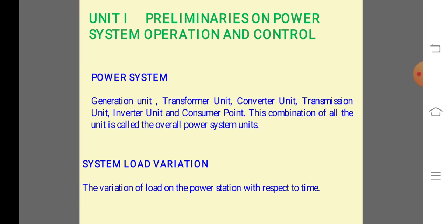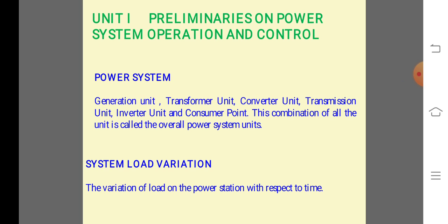The governor senses the speed and gives a command signal. Governor control is used to control the speed of a prime mover. A governor protects the prime mover from overspeed and keeps the prime mover speed at or near the desired revolutions per minute when a prime mover drives an alternator supplying electrical power at a given frequency.